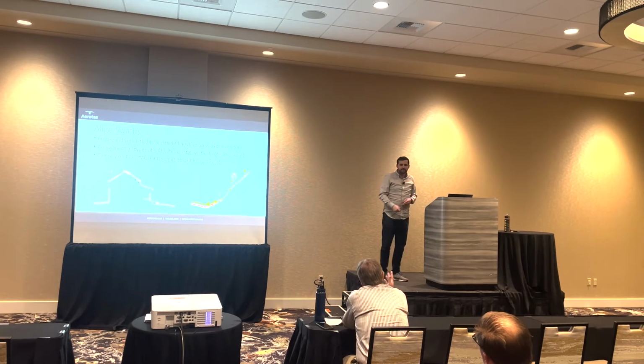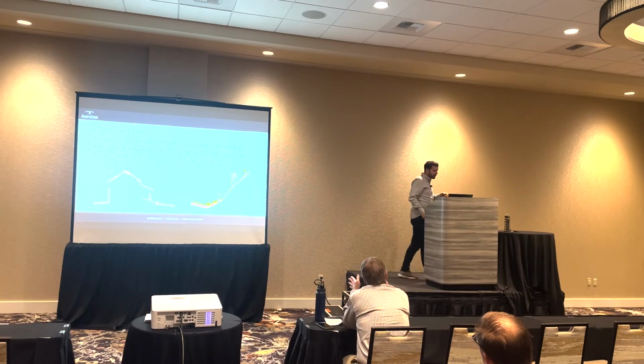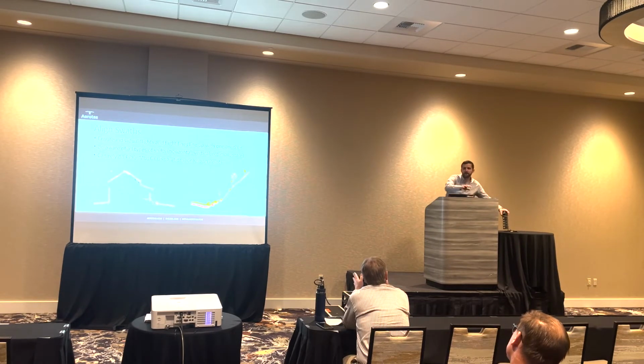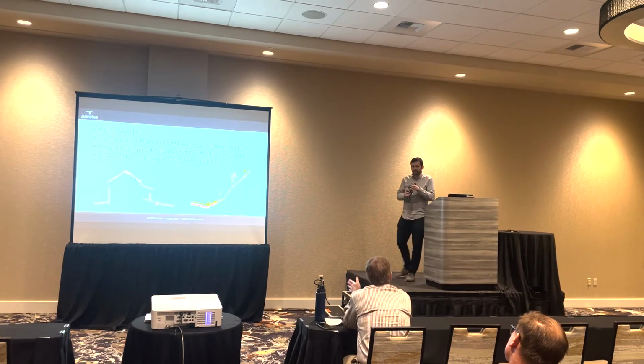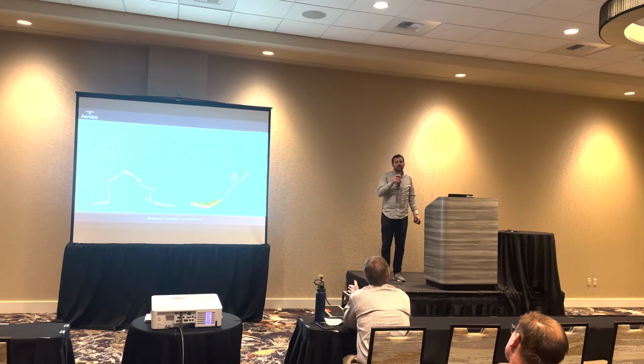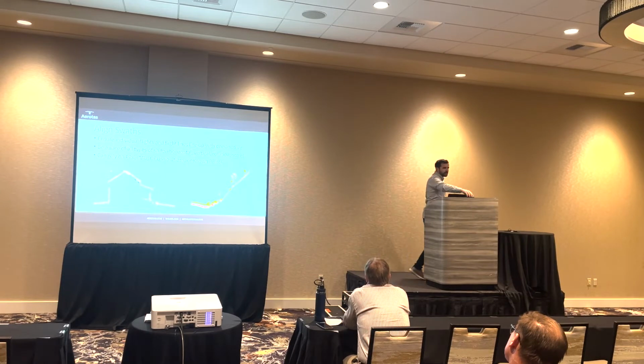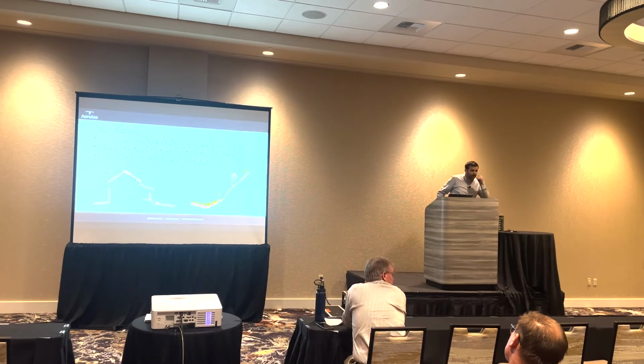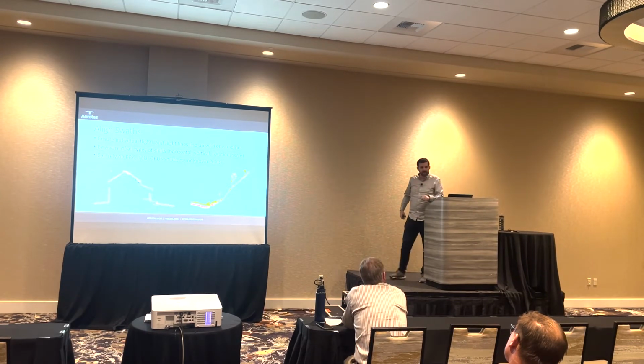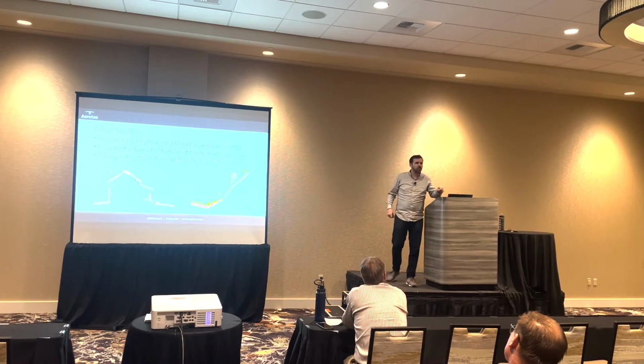So, are you saying it's logging data as you fly, and then you're post-processing that data to get your coordinates? Is that correct? Yep, that's how we work. And I heard that the PPK, the post-process kinematic, is a little bit more accurate than the real-time kinematic if you're broadcasting corrections. Is that correct? Yes.